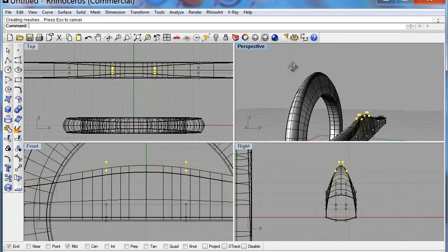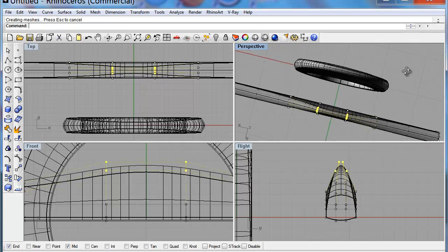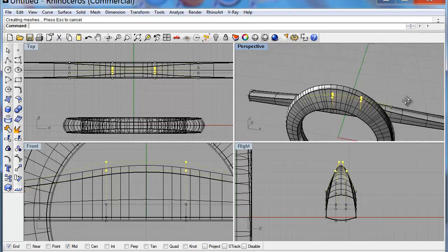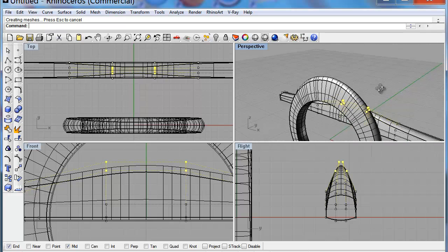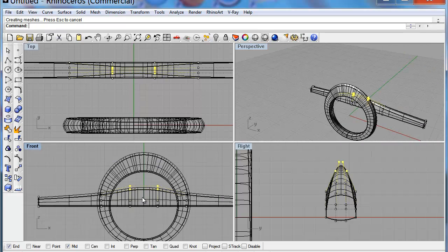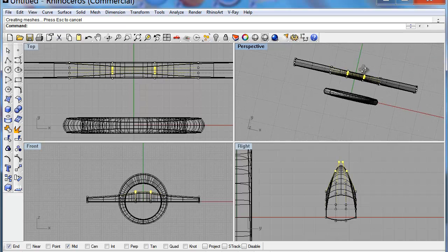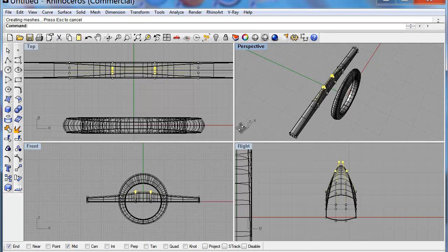Okay. So it's kind of almost like sculpting, if you want to think about it like that. You're pushing, pulling the points on that flat section, and the reason I'm doing this on the flat section is because while this is down here and it's using history to float back up onto there, no matter what I poke with over here, as long as I don't touch the bottom points, my finger size will always stay the same. Alright, so let's do something that's not uniform.